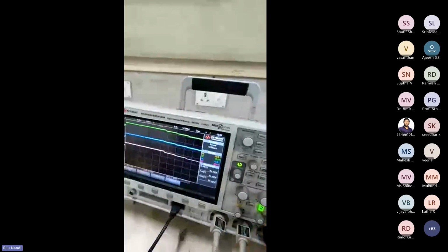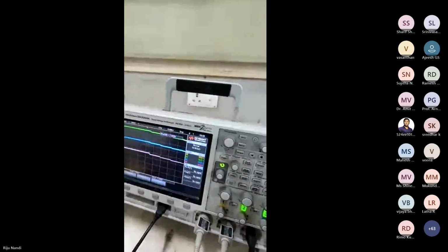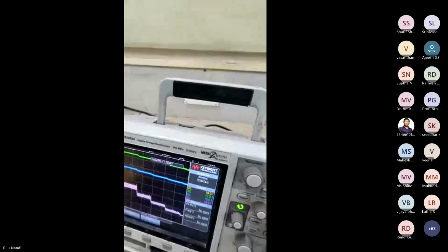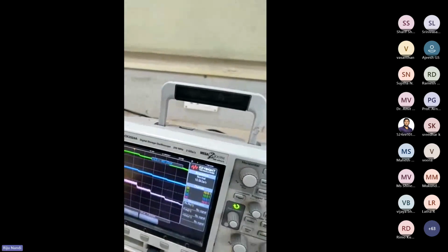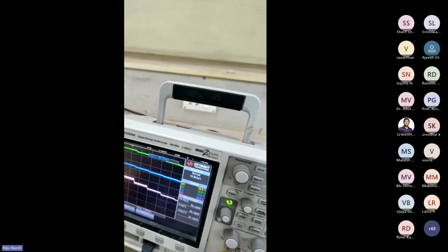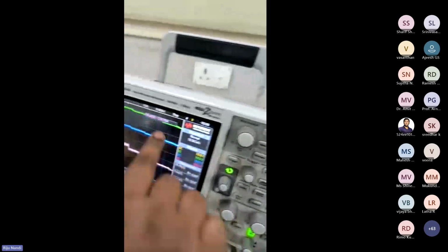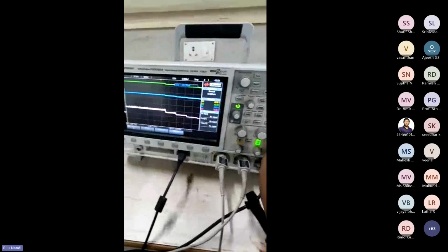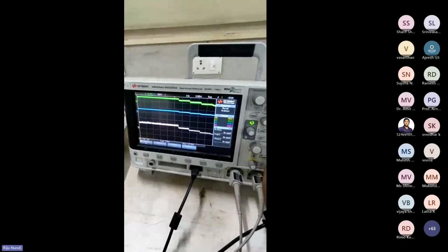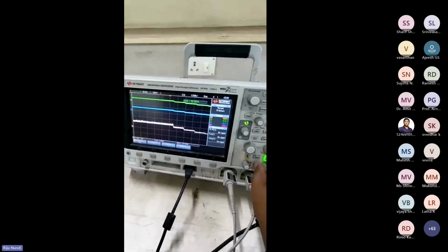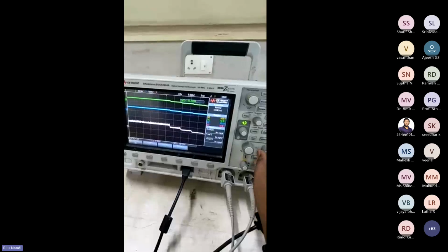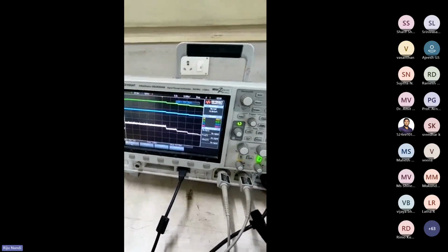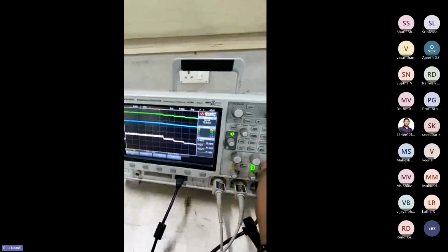You can see that value, that power also. This is the power, the last position. This is the current. The 3 is the current and 2 is the voltage. And voltage is around 7 to 7.5 volt, and current is a little bit, 0.1 ampere, and power is the same like that.